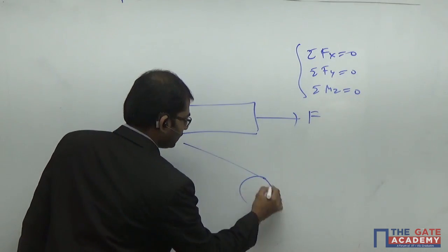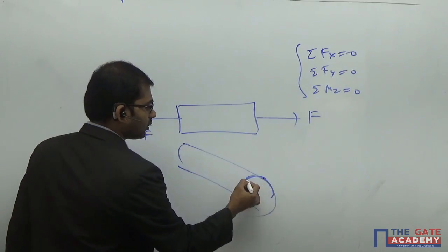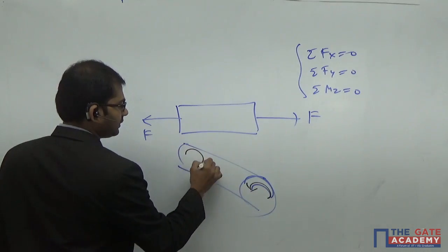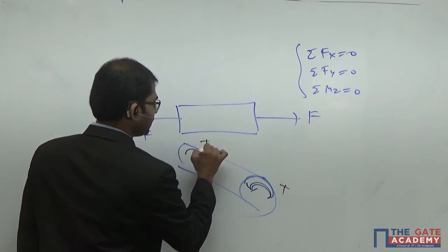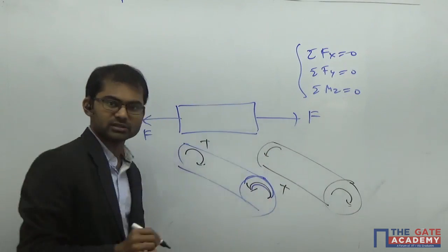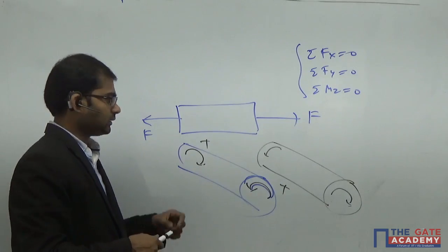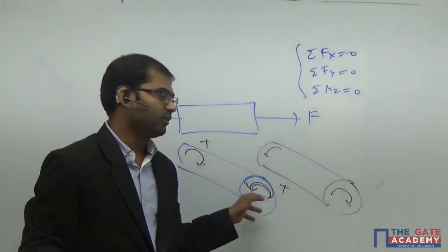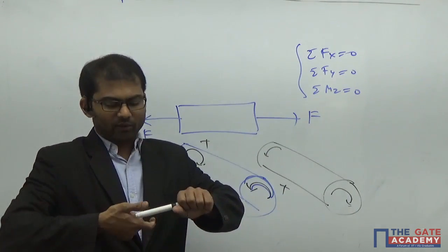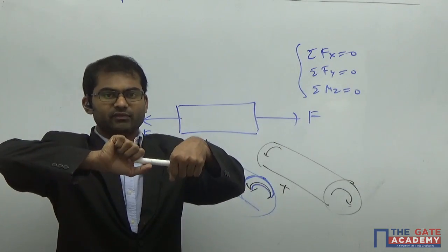In the same way, if any shaft or torsion member is experiencing an anti-clockwise torque on one face, I have to create a reverse torque of the same magnitude on the other side. Or the reverse can also occur: if it is clockwise here, I have to put it anti-clockwise there. Over the length of the shaft or torsional member, it is not compulsory every time to use a shaft, but the concepts are very simple to understand using a shaft. So although on one side I'm trying to rotate in the anti-clockwise sense, the other side will try to cancel that effect.